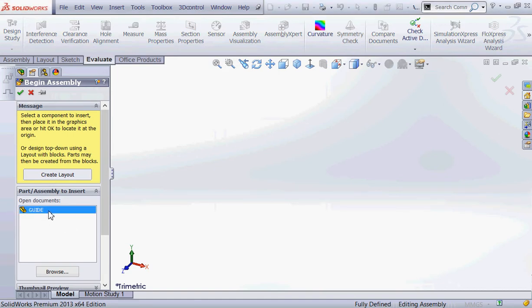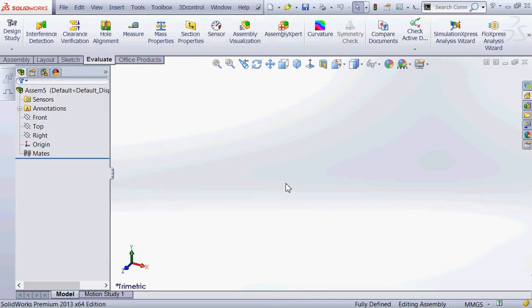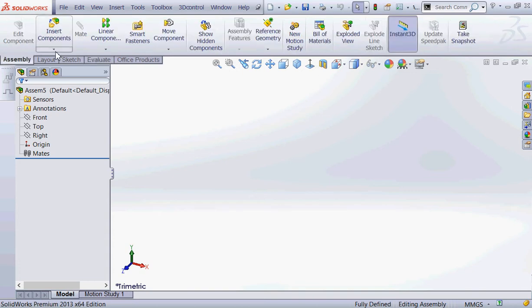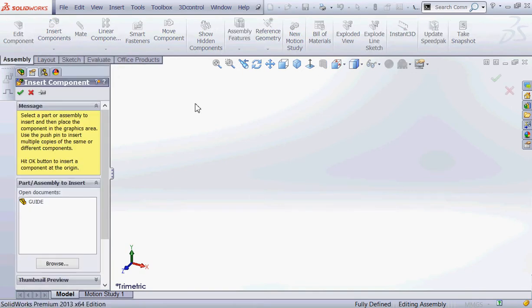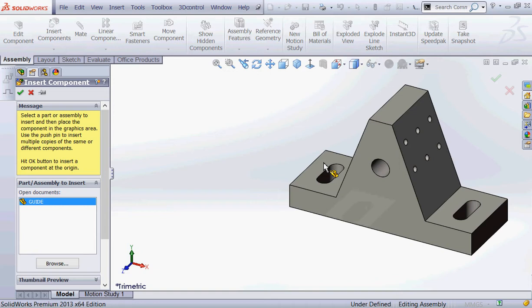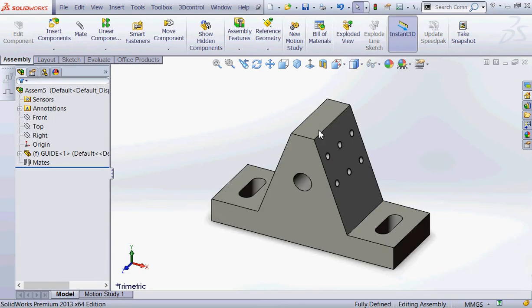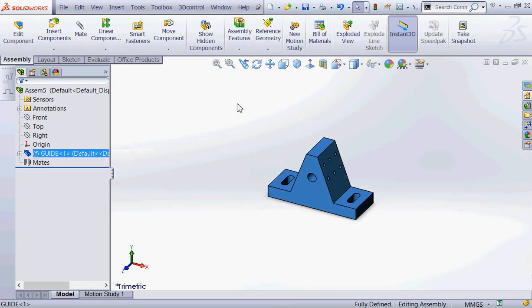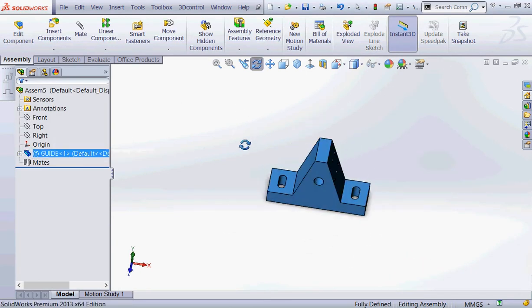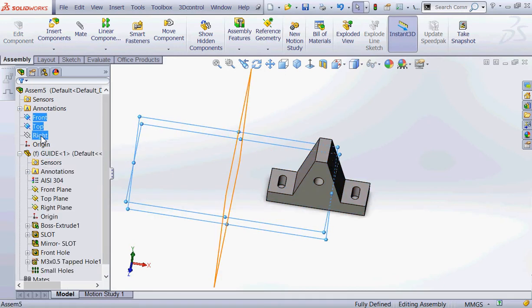Okay, so now I've shown you 3 different ways to create your assembly. Way number 1, drag the part in from Windows Explorer. Way number 2, open your assembly template, create the part, and bring in the part. Way number 3, open the part, make new assembly from the main part. I don't care which way you do it. All right, but you all should start with the guide.